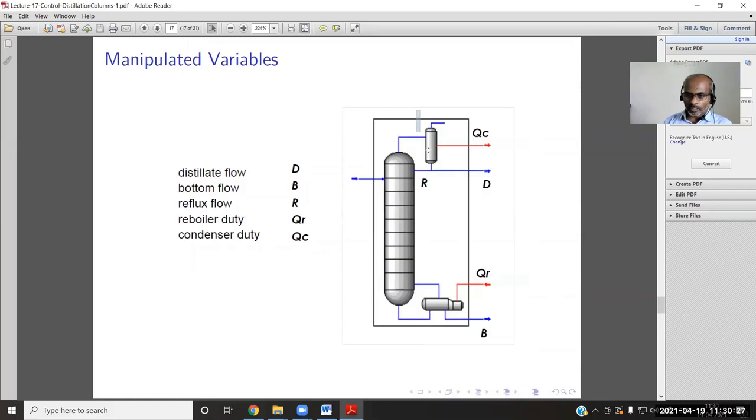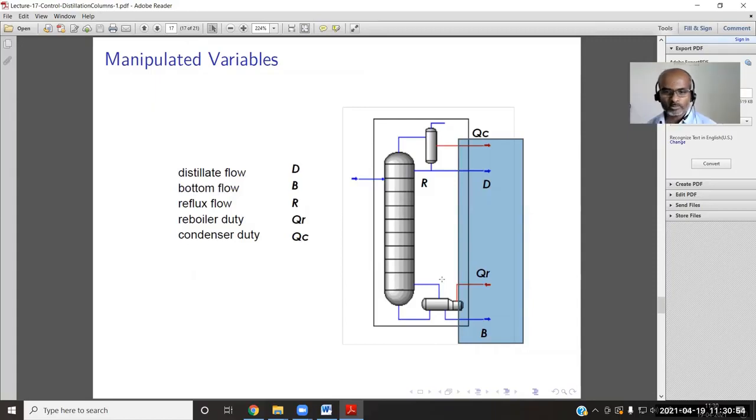So the top corresponds to the condensing conditions and the bottom to the reboiler. The light component is at the top and the heavy component at the bottom. Suppose you want to carry out this operation in an isothermal manner, what pressure variation would there be? For isobaric the temperature decreases from bottom to top. What should be done for isothermal?